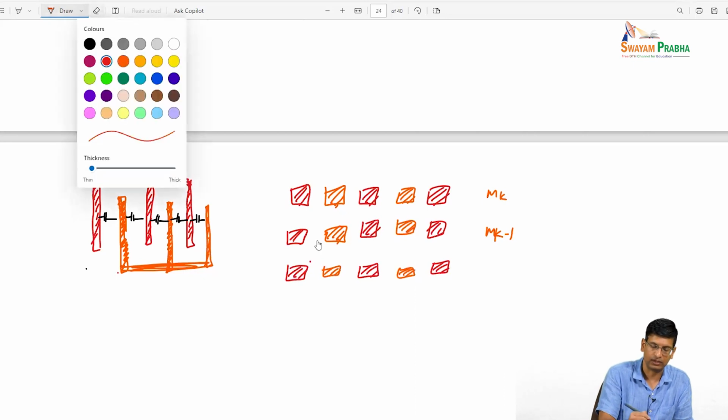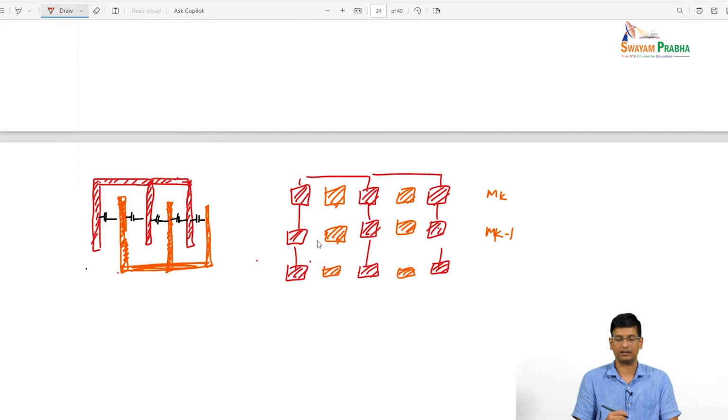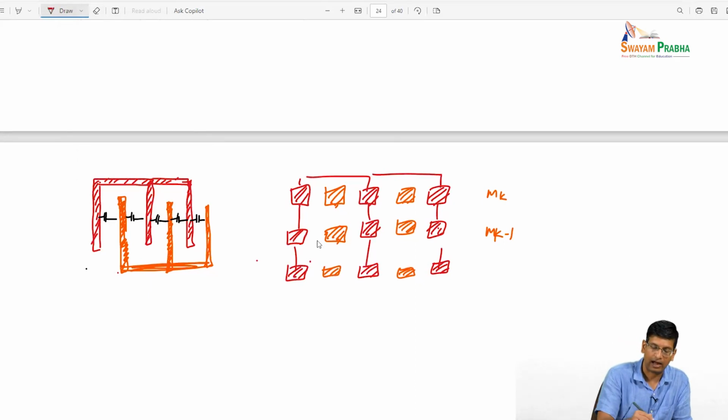You have to imagine that all of these are wired together, right, in some way across metal layers, and similarly the other metals are wired together. So you have all of these capacitances that exist, right? So now you're using multiple metal layers to create these capacitances.